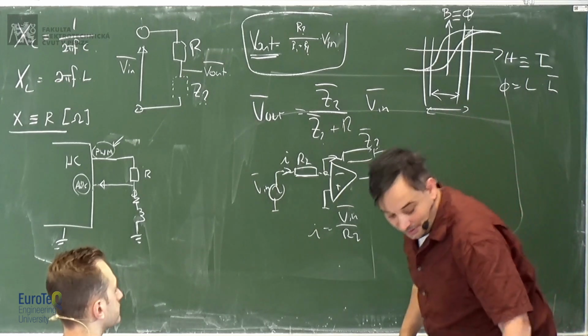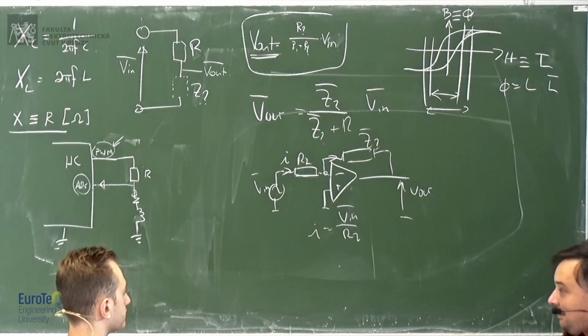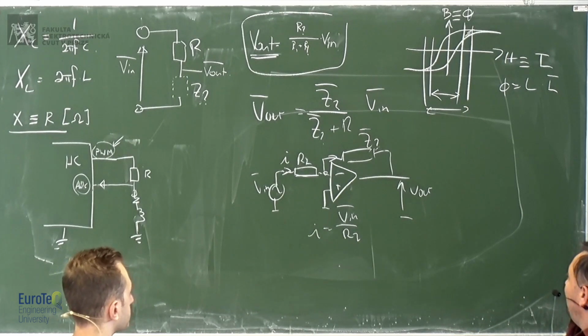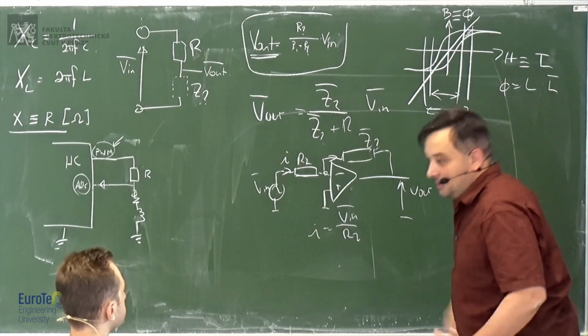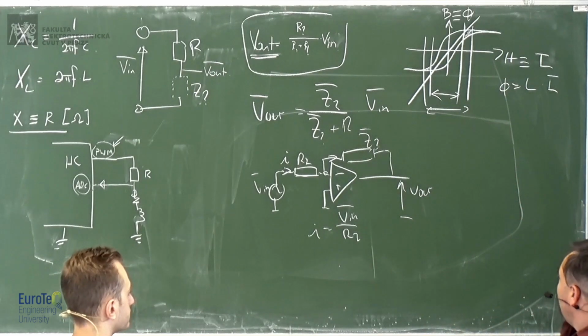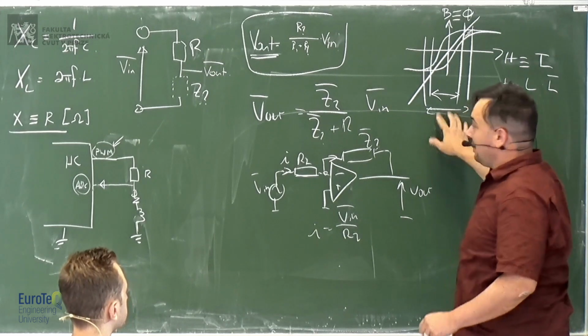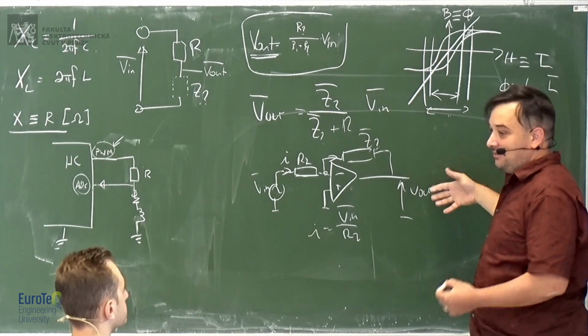In fact, when you measure with some LCR bridge and you change the current, and you go to the extremes of the BH loop, you see that the impedance changes also with the current, okay? Of course, if you have a relationship like that, it's not a problem, okay? But if you have a BH loop which is far from being linear, then you have a measurement which depends on the current that you inject, which is not so nice because you want the current to be always the same to have a reference.